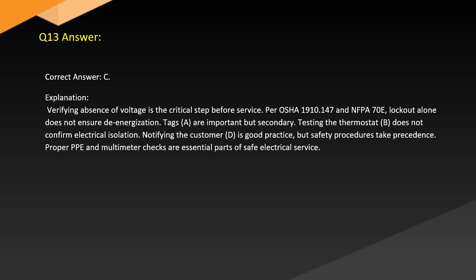Testing the thermostat (B) does not confirm electrical isolation. Notifying the customer (D) is good practice, but safety procedures take precedence. Proper PPE and a multimeter are essential parts of safe electrical service.